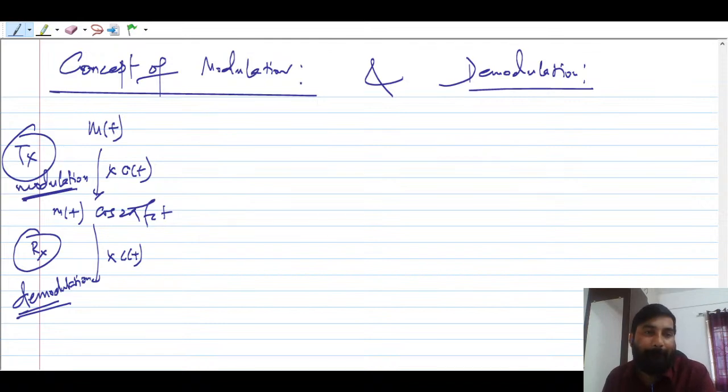And then after multiplication of the carrier, you have to pass it through low pass filter, because low pass filter is going to pass only low frequency signal and reject high frequency, unwanted one, right? Because after all, your massive signal is centering around low frequency, that is a baseband signal. So how do we obtain signal back from the band pass signal? Basically we'll pass it through low pass filter. So remember, in both cases we are multiplying what? Carrier.